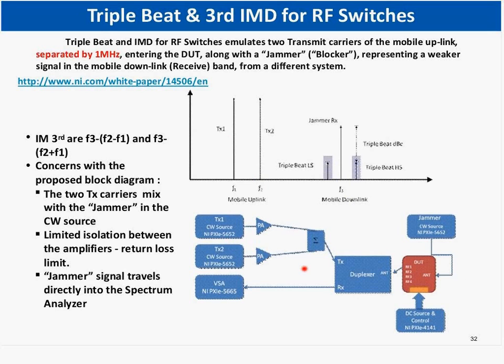First thing, we observe the 2 amplifiers with the 3 dB hybrid, and we remember what we said about that. And then we see a duplexer here. Probably the TX will have to have a lot of rejection to block IMDs that are being created here. And then we see a jammer that injects the signal into the device under test on the opposite port. What we see also is that the TX signal that goes into the device under test actually has nowhere to go but into the jammer source. So that's something that should bother us.